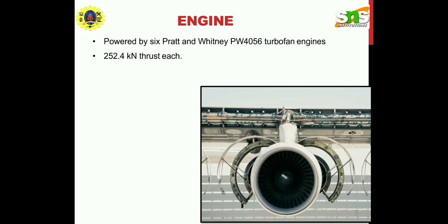When the path of the flow is wholly or mainly parallel to the axis of rotation, the device is termed an axial flow turbo machine. The radial component of the fluid velocity is negligible. Since there is no change in the direction of the fluid, several axial stages can be used to increase power output. A Kaplan turbine is an example of an axial flow turbine.